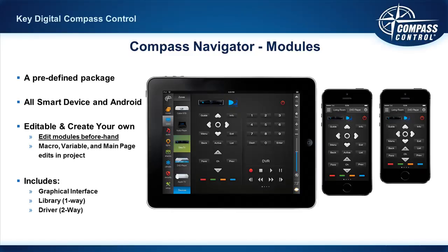So looking a little more at a module, what is a module? Well, a module is not just a library of commands or a code set, okay? It is a code set that has a graphical package. Of course, all of those buttons that you see have the correct commands automatically mapped onto that. If you have a bidirectional module like a lighting feedback and thermostat feedback and metadata from an audio streamer, then of course there's a bidirectional driver that is automatically compiled and attached to the various graphical elements.